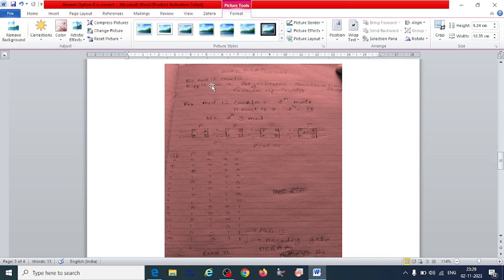So for mod 12 counter, triple counter, asynchronous counter, that means J equal to K equal to 1. Then for mod 12 counter, 2 to the power n, n must be 4, 2 to the power 4 is equal to 16, 2 to the power n must be greater than or equal to mod.